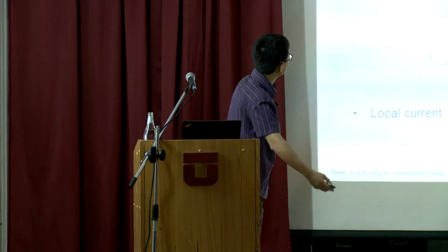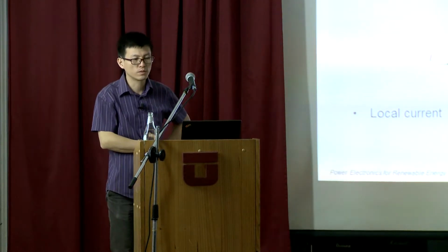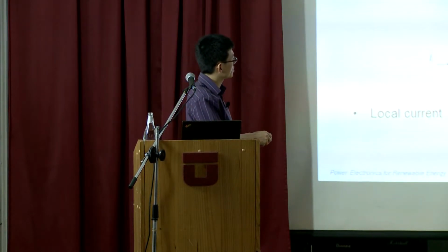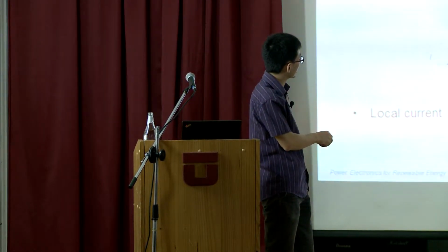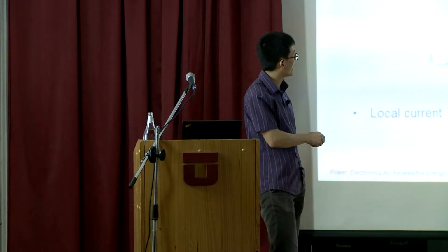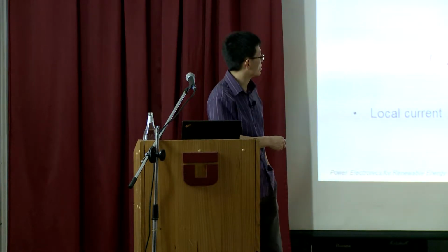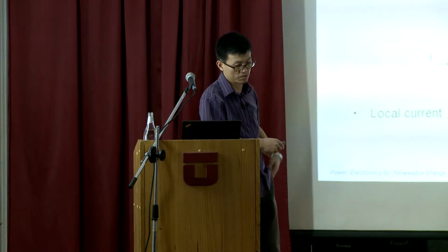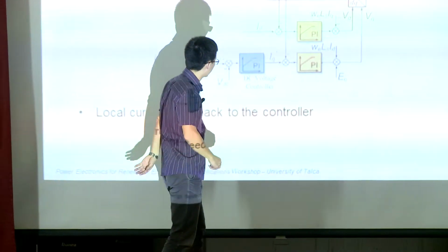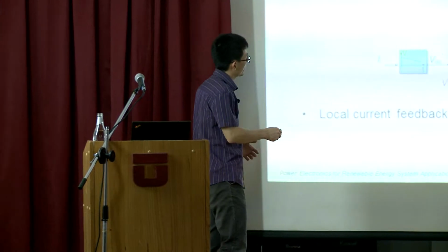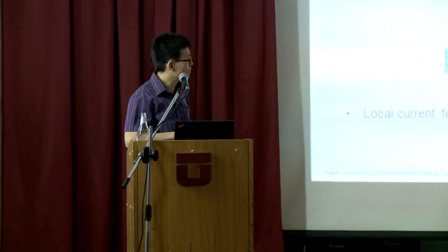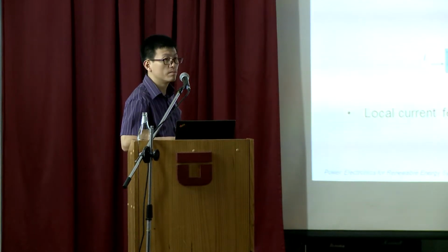Okay. So if we use this droop concept for our AC/DC system, what's going to look like is just this block. All the rest you'll find are the same. I didn't change this at all. So there are 2 PI current loops. As I said, this current loop controls the ID and IQ. One controls the flux, this one controls the torque, or the active power. This controls the reactive power, this is active power.